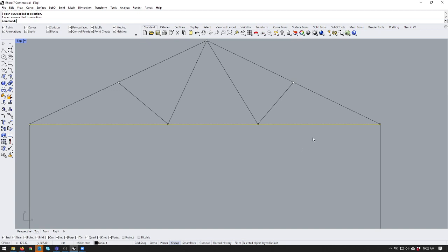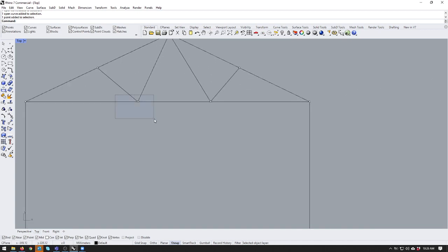Yep. I've touched on the subject that these particular connections can have properties on them. Karamba doesn't actually work this way, but we'll get into that in a moment. So we can say whether they are rigid or pinned, or we can also control the axis of freedom of movement. Think about your elbow: it can torsion in a way, and it can rotate in one axis, but it can't rotate in the other. It's your shoulder that ends up doing that. So you can limit the freedom of movement with these things as well.